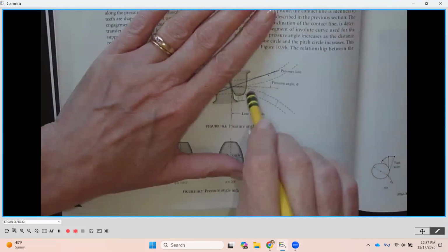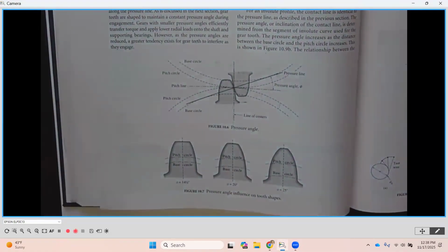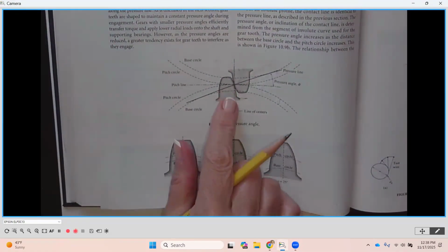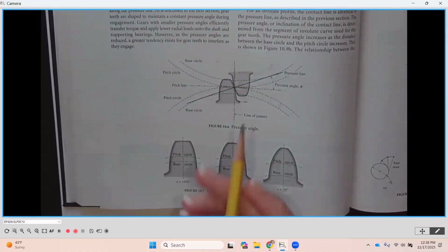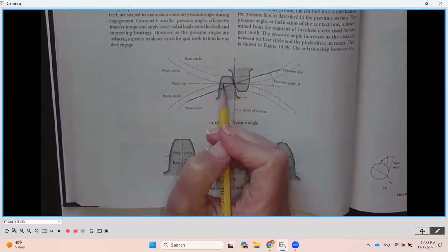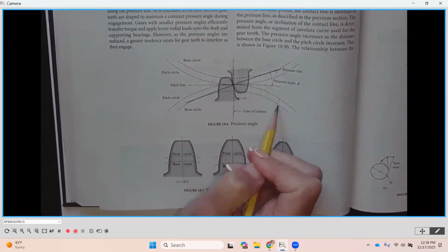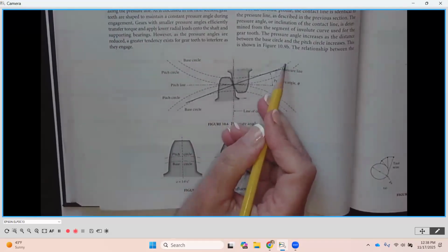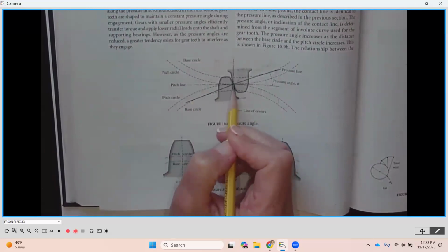We identified this where we showed how, when the two teeth come together, the addendum, the top of the tooth, sneaks down into the bottom of the tooth, which is called the dedendum, and that difference is going to be our clearance. Where they come together and hit one another is the pitch circle, the pitch diameter for the bottom gear, and the pitch diameter for the upper gear. That's where everything comes together.